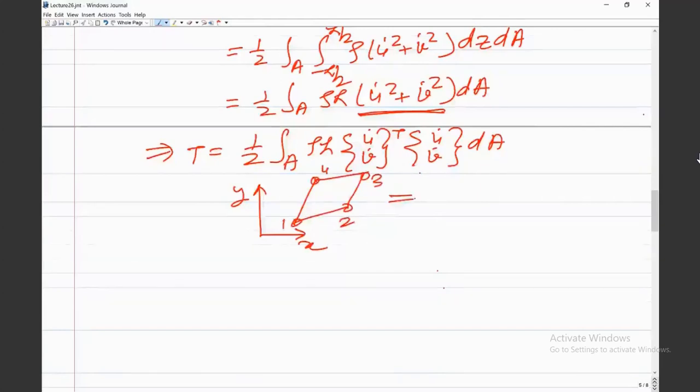And this is mapped to a square in the natural coordinate space. So we'll have xi and eta. Nodes are 1, 2, 3, and 4, and at each node the degrees of freedom are u1, v1, u2, v2, and so on. So these are the degrees of freedom.